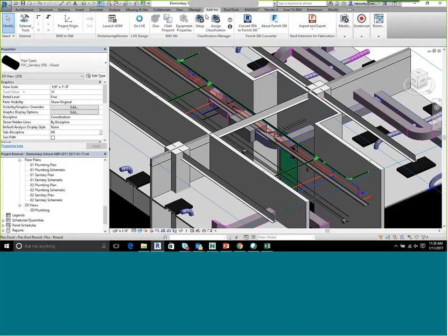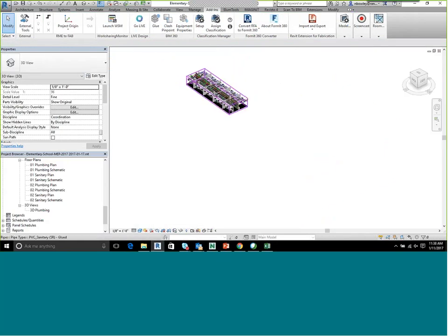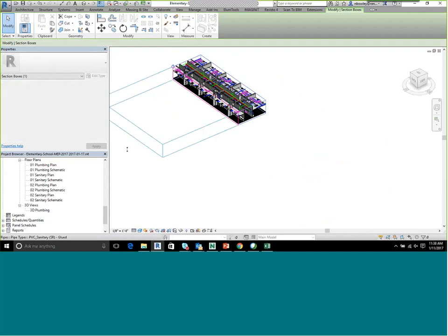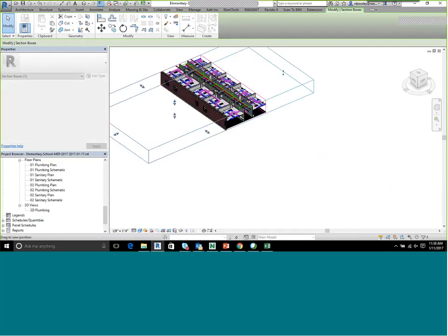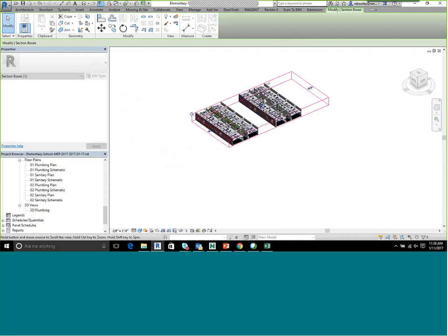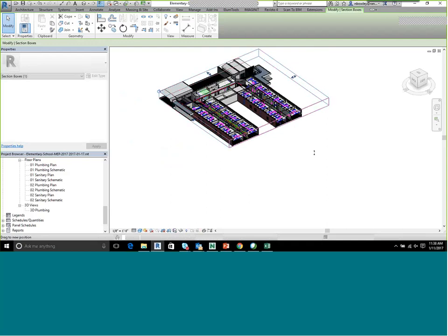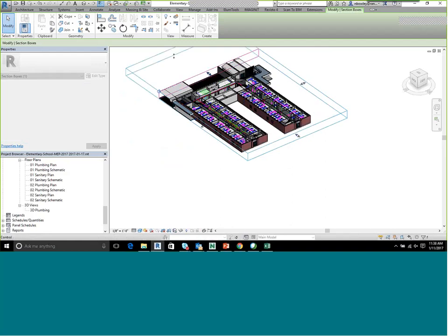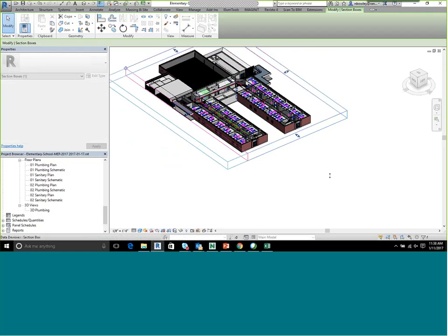Go into Revit. And then hopefully knowing that it's first floor clashes, I would just have a 3D view of the entire floor plan. Maybe I'll just extend this out. Can't remember what part of the building I'm on. Oh, okay. I got rotated around too much. So maybe knowing it's on the first floor but not knowing the area it's in, I'll just extend my 3D view to include the entire first floor, where I can easily see the clashes and I can easily see other disciplines, versus just a plumbing plan, where I might only see plumbing. I don't even know what it's clashing against. That's why I like these views.